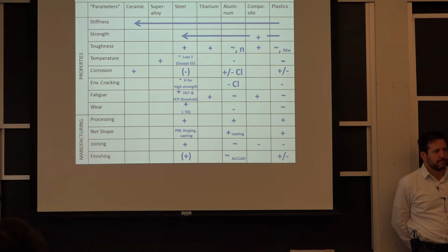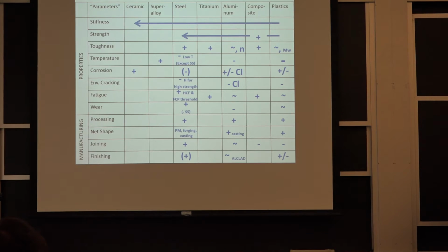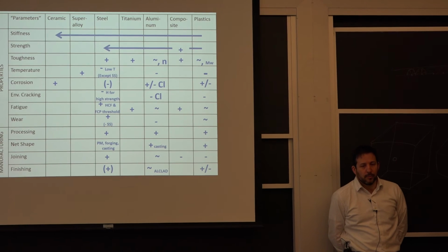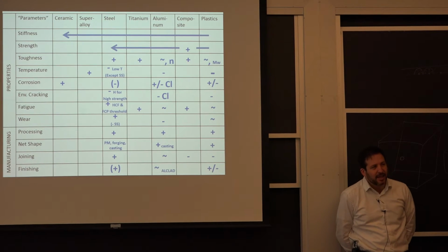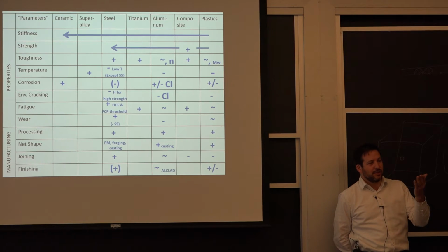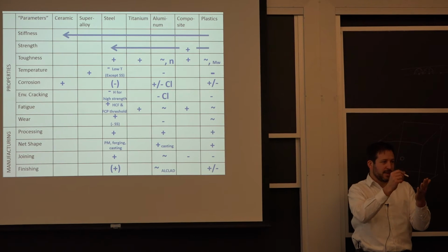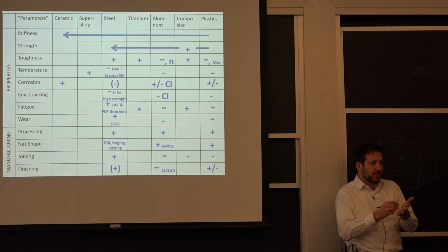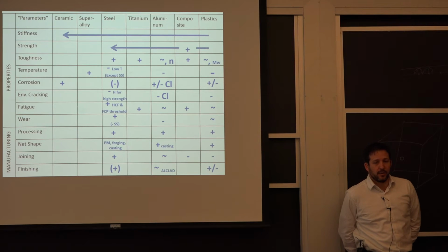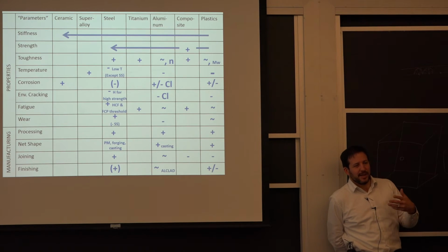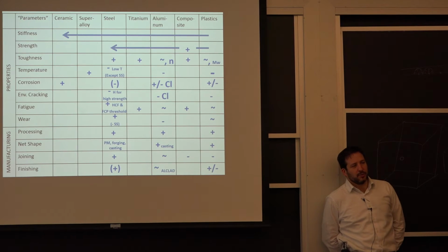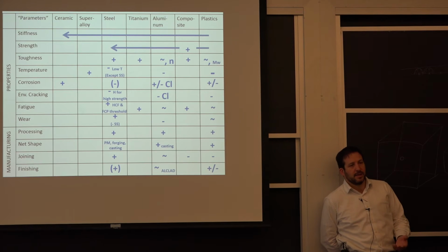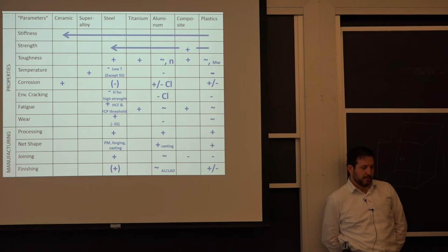Yes? Is there anything that can be done to coat plastics to prevent UV degradation? Yes, very good question. It was about protecting against UV degradation. One of the common ways is you put carbon black into your resin, and it's essentially a shield. So it's only the top surface that the sun rays are going to get to, and they get stopped right there. That's a practical way. In terms of really putting something on the outside, not very common from what I know, but you could essentially have a two-layer structure made by extrusion that will have the outside layer with carbon black. But what I've seen mostly is fittings that do have that, so it's only the very outside that's affected. Very good question.